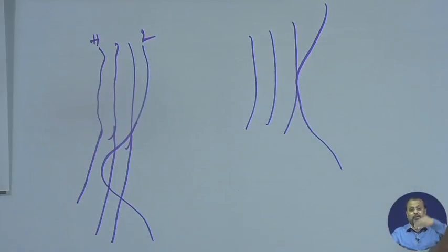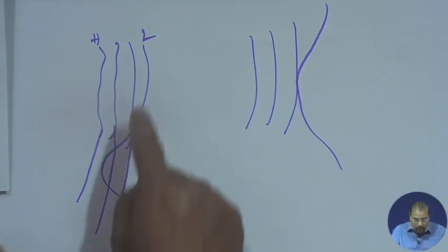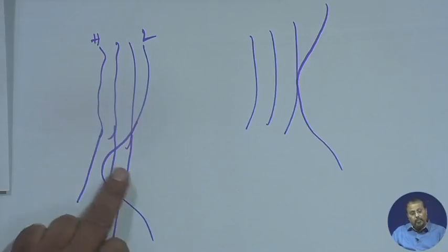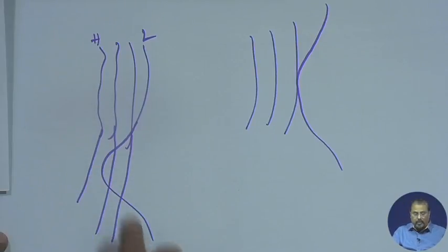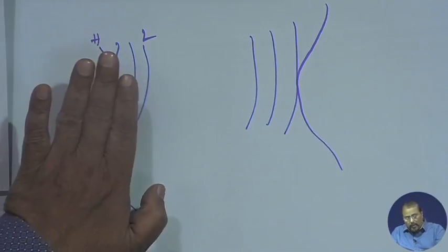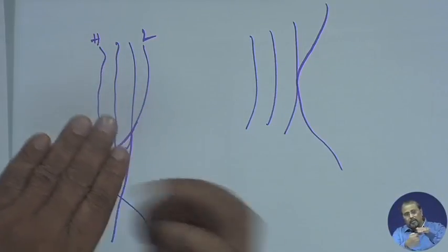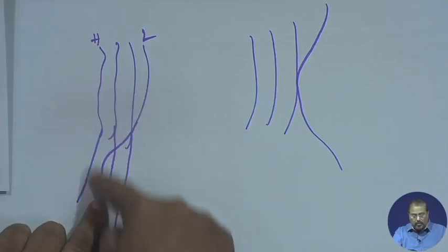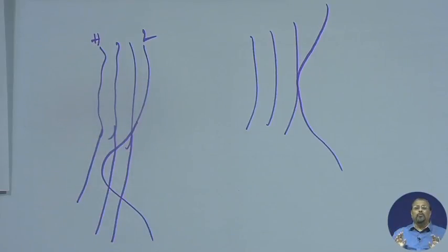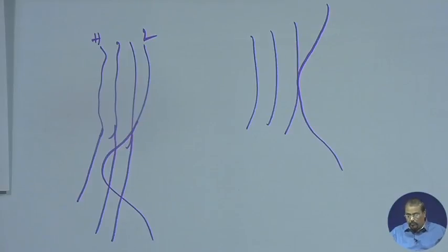So, there is a vertical face. Keep that in mind in the contour analysis. And if it is entering into this, then there must be a cave: this is overhanging, and the lower level contour has entered into it as a cave. So, this is the cave situation. If you understand this, then your contour interpretation will be very, very effective.